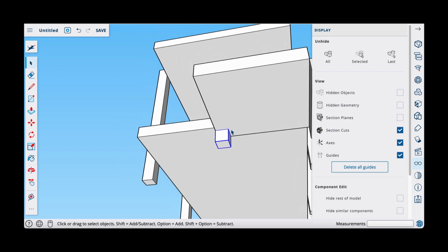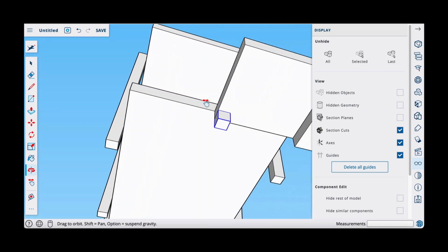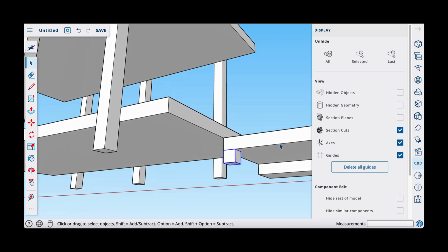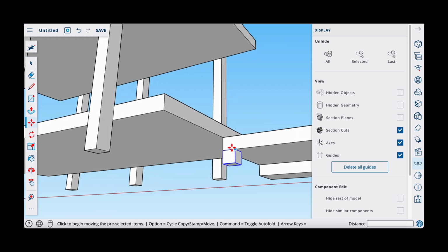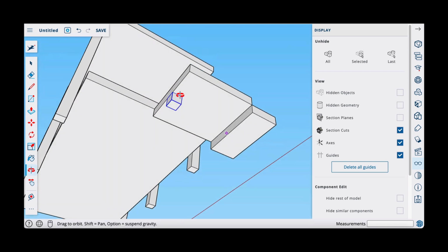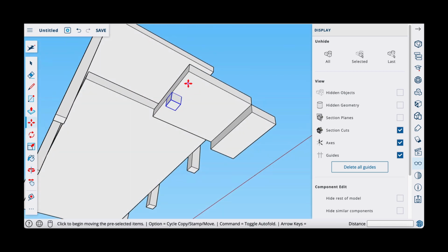Alright, so I got to move it to the center. So I'll do that in 2 steps. First step is to move it to the midpoint of this edge. So I'll use the move tool, and I'll move it from the midpoint of the little column here to the midpoint of the landing, which is that dot right there, midpoint. Alright, click and release. And now I'll move it in the green direction from anywhere, but I'll move it starting from here.